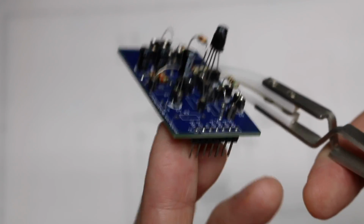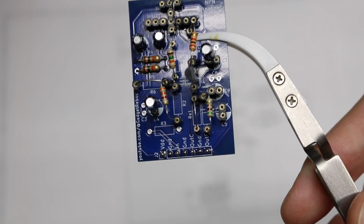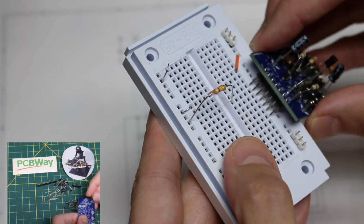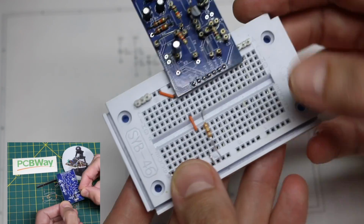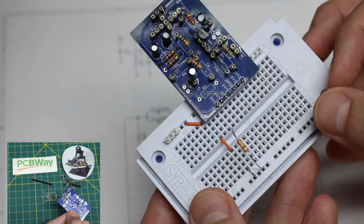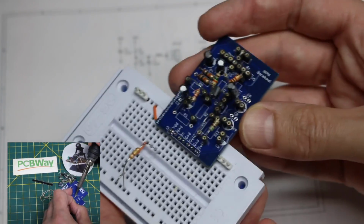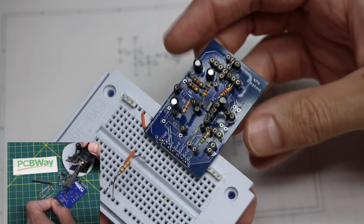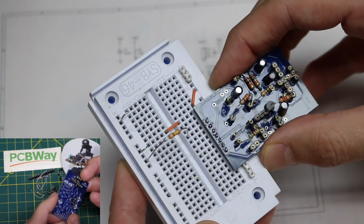And there's a bunch of headers here for a breadboard, so I can power the board, send in a test signal, and get the output signal all on the header pins. So I can just plug this into a breadboard and have this self-contained module. Sometimes trying to just build the simple circuit on a breadboard, the parts are too close together, or the leads may touch and short out a lot easier. So this may sometimes help with that, but if a standard circuit block is designed, then I can just commit the part values on here and plug this board in when I need a quick transistor amplifier circuit.